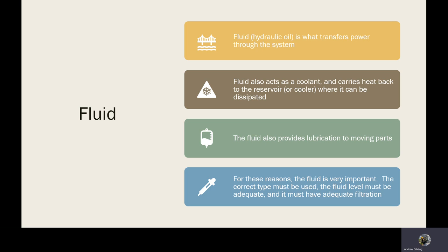However, a system that's been running on mineral oil with booms and has never ever leaked and has been dependable for years and is producing great power, you drain the oil out of that and put in synthetic oil, it will start to run very badly, very quickly, and leak everywhere. A lot of the deposits from the natural fluids, from the mineral oil fluids, get into all those little places where they need to be. As the machine wears, it's almost like that crud just kind of goes in those little crevices and just makes the machine function so much better.